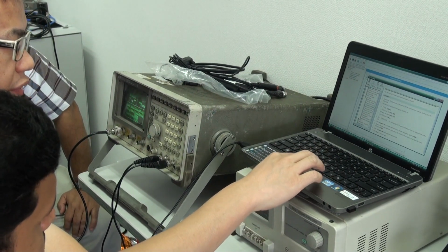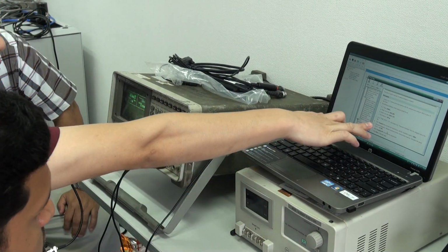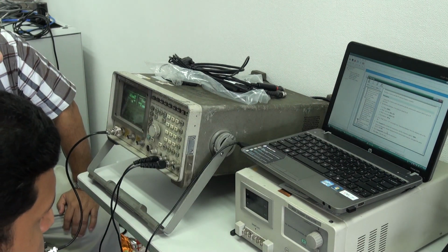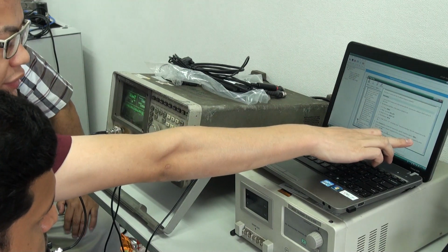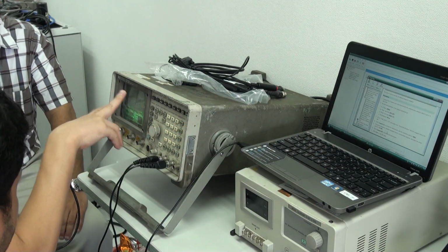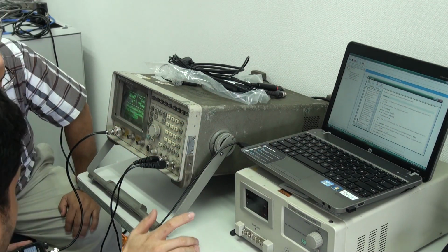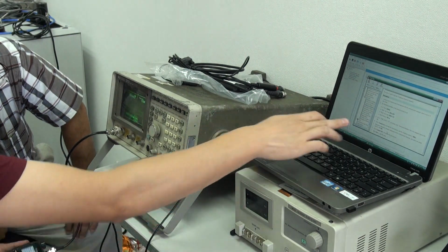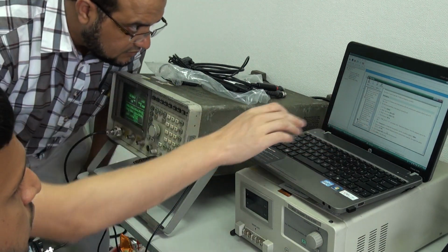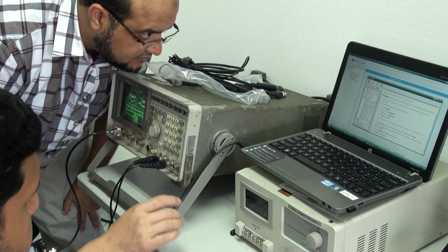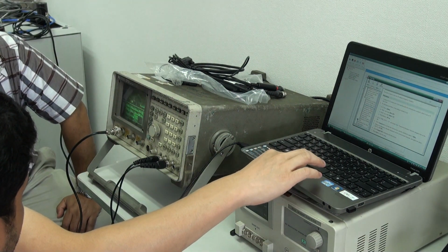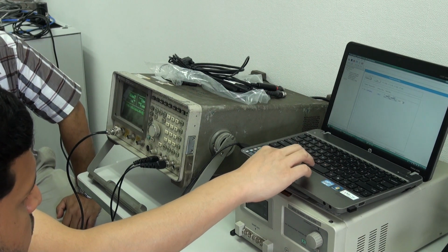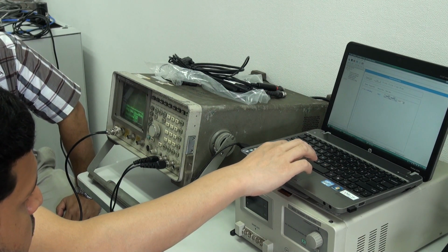And then you can transmit, and then you just click transmit on to activate transmission. Okay. And the modulation signal is 100 hertz, which is coming out from the emitter. And you can observe the deviation. It should be around plus or minus, the maximum, plus and minus 5 kilohertz. Okay. Then you just turn it off.